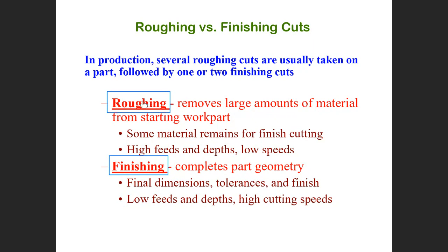High depths of cut, high feed rate, and low speed. Because if you have high speed, then the tool will be broken. Then high depths of cut and high feed rate to remove a big amount.